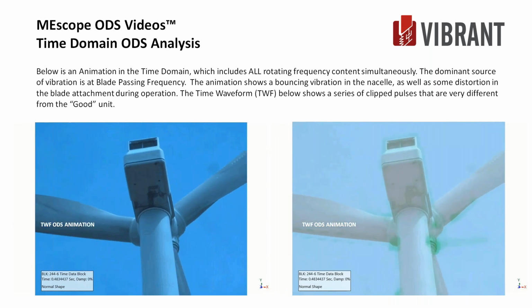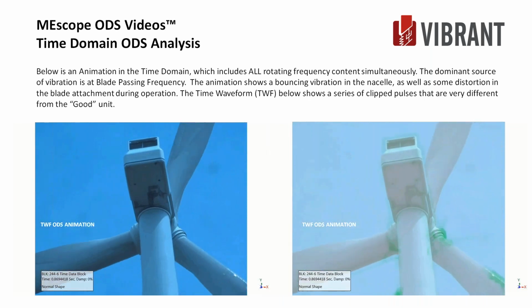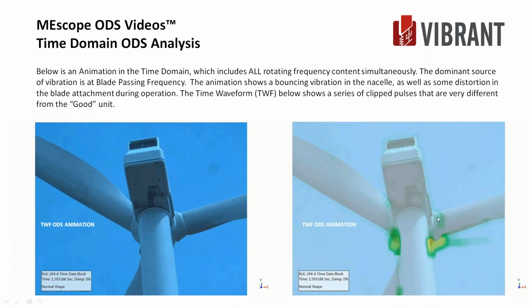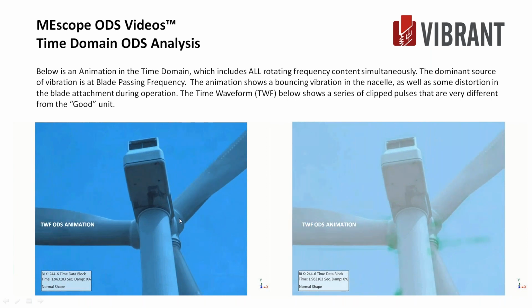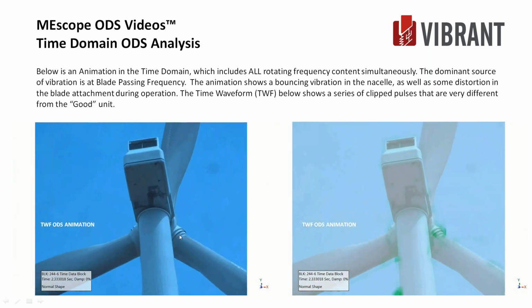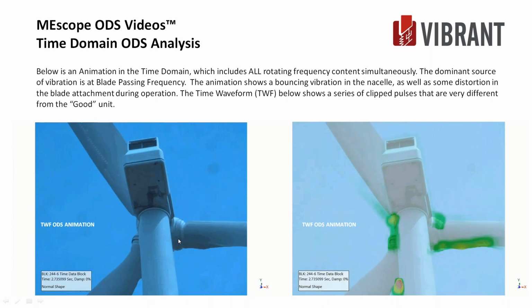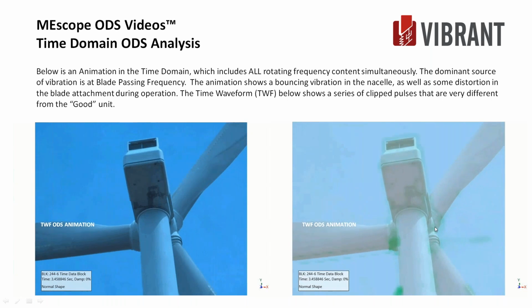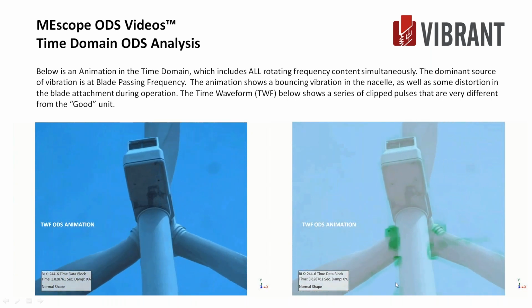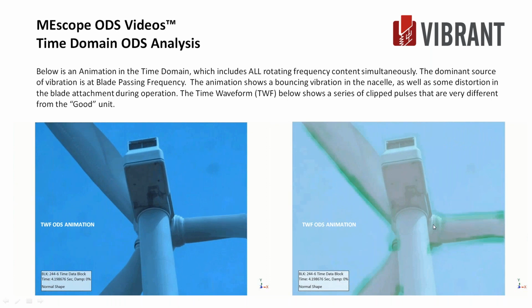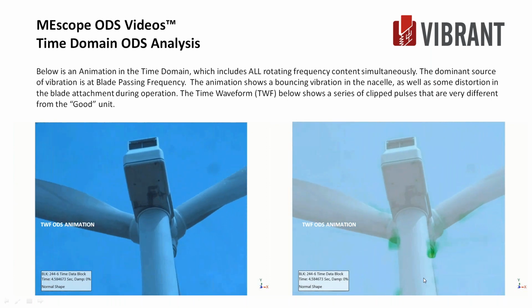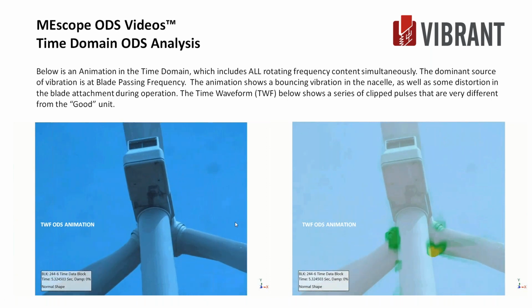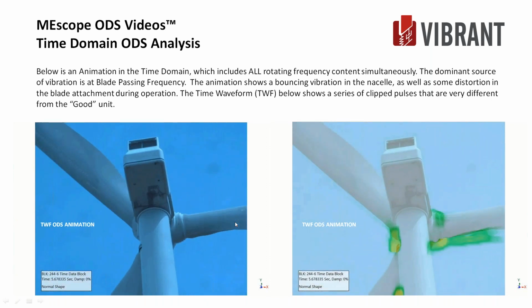This is that motion in the nacelle, or not the nacelle, but the nose cone joints there where the pitch blade bearings are. And you can see the non-color one, you'll see some distortion as they walk through here, as they go by the tower. And here you see it in color a little bit to highlight what's going on. So all three of those joints are moving. So you do get a lot of motion from the blade pass frequency in the tower.